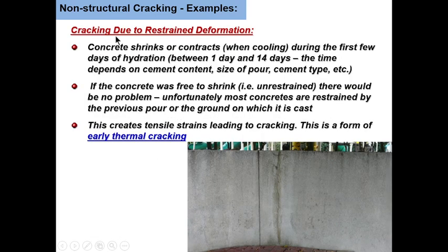You also have cracks due to restrained deformation. You can see a mass of concrete here, and because the mass of concrete is very large, when expansion wants to take place, there is no space for expansion, so it will cause cracks. And this can easily be avoided by the provision of an expansion gap.